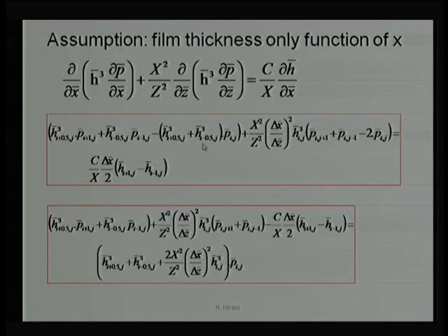We know there are p(i, j) terms in the first bracket as well as in the second bracket, and we require the value of p(i, j). That means we need to take this common, or sum these two terms, and both are negative. So, we can take it on the right hand side, and the right hand side term after summing becomes something like this: